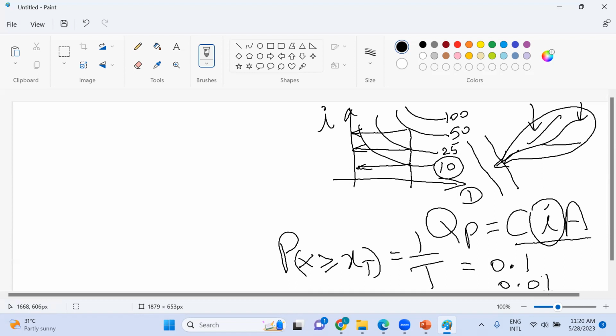So if you use this rainfall intensity in your design, now you are safer than using a smaller return period. So you understand that concept, right? If you are using a larger return period, then you are talking about a larger rainfall intensity. That larger rainfall intensity means larger peak flow. Larger peak flow means your cross section, your channel, can handle a larger flow rate.